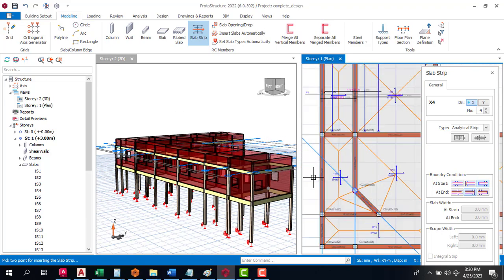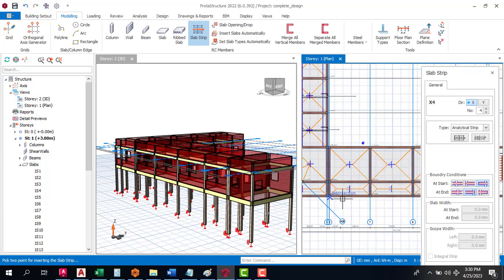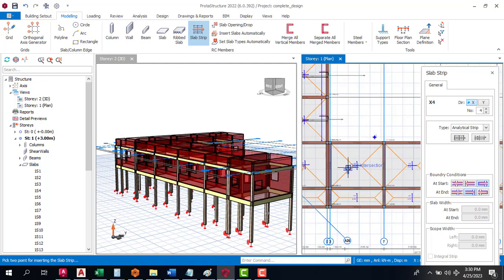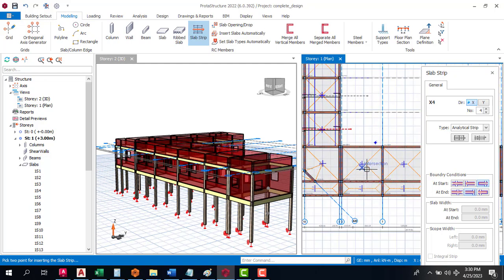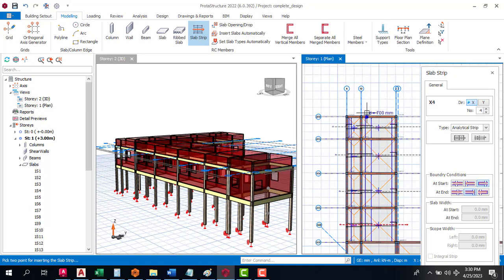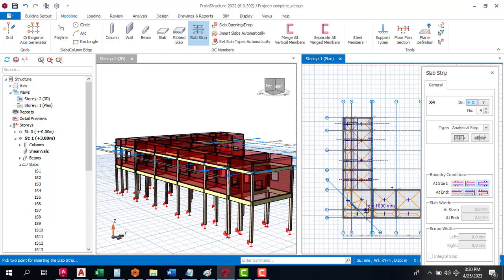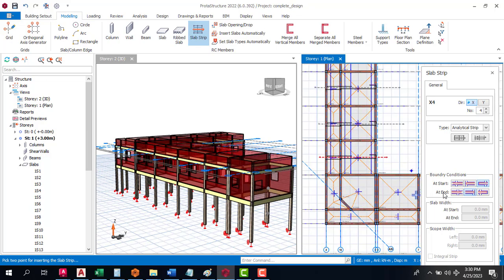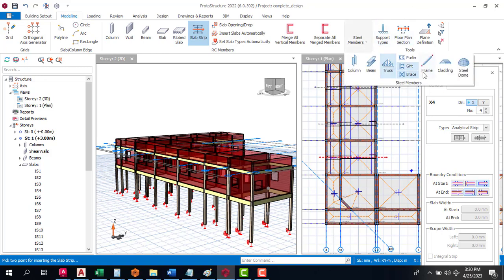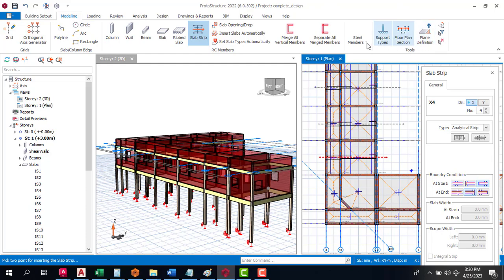So you have to actually make sure that it's sufficient. Okay, so these are the things you have to always put in order. You have to check the thickness of your reinforcement. You have to check the spacing of the reinforcement. You also have to check the thickness of that particular slab.